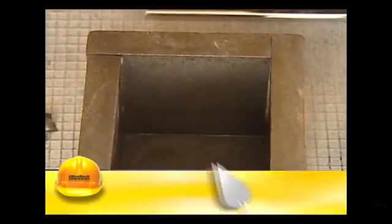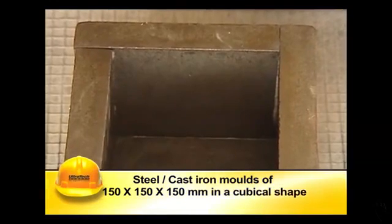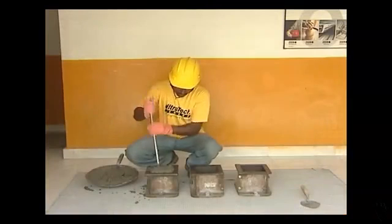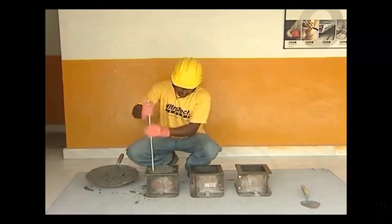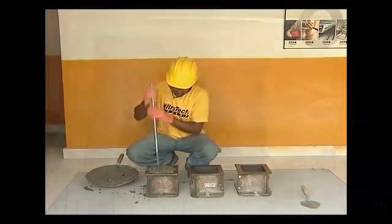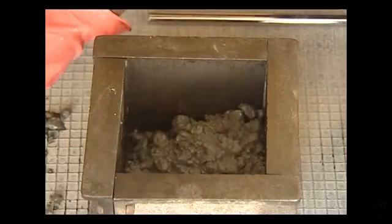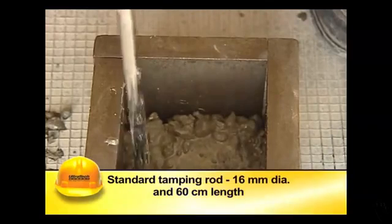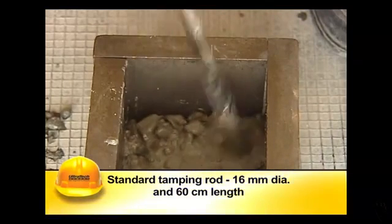Generally, specimens are cast in steel or cast iron molds of 150 by 150 by 150 millimeters. The mold should have rigid connection with base, essential in order to prevent the leakage of mortar during compaction. The cube is filled with fresh concrete in 3 layers and compacted well using standard tamping rod of 16 millimeter diameter and 60 centimeters long.